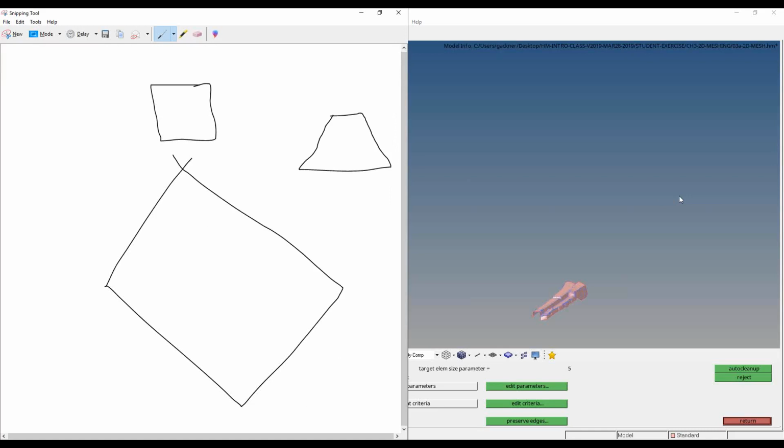But more than anything, because of things like not using a uniform element size, or because you're doing different meshing strategies at different parts, when you're looking at a high stress region, you should feel good that it's a high stress region, but the thing I'd be most concerned with is how much high stress that is relative to another section on the part. And more so than any individual element quality, which we're going to get into next, it's that consistency throughout the part that's probably the most important thing for any given mesh.